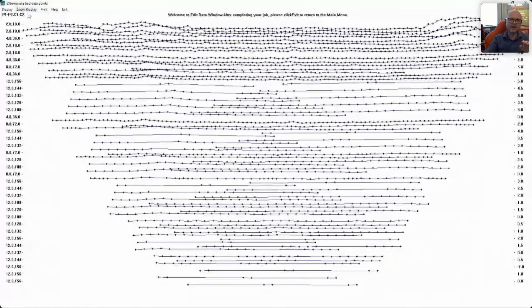What should happen here is that the resistivity values represented are not absolute, they're relative from one data point to the next. So you wouldn't expect to see a big jump in resistivity. And if we did, that would suggest it's a spike, a poor data value, and we could therefore try and remove it from this data set.